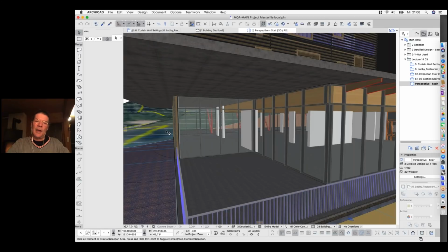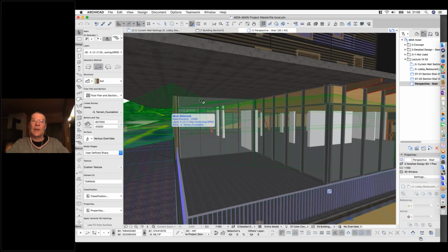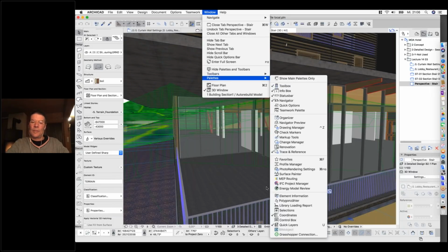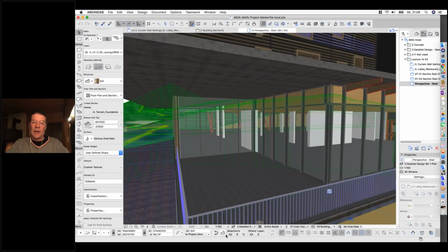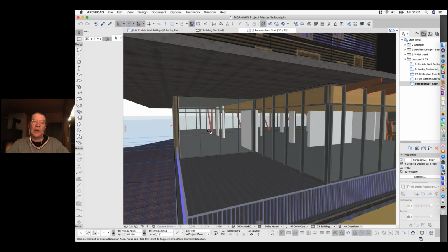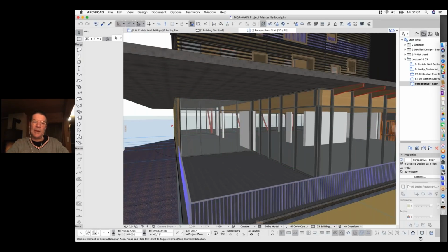First of all, let me switch off the layer of my landscape. Usually I use for that one the quick layers, which are placed down here. And I can say, just select the mesh of the landscape, and I say selections layer should be invisible now, which will speed up the 3D process a lot. Okay.